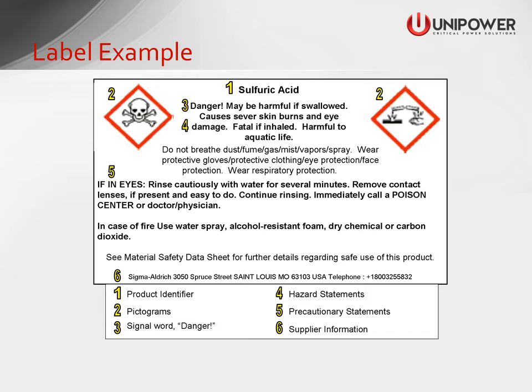Do not breathe dust, fumes, gas, mist, vapors, or spray. Wear protective gloves, protective clothing, eye protection, face protection. Wear respiratory protection. If in eyes, rinse cautiously with water for several minutes. Remove contact lens if present and easy to do. Continue to rinse. Immediately call for a poison control or doctor or physician. In case of fire, use water spray, alcohol-resistant foam, dry chemical, or carbon dioxide.